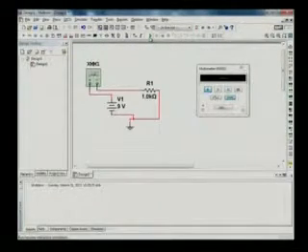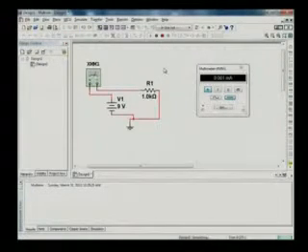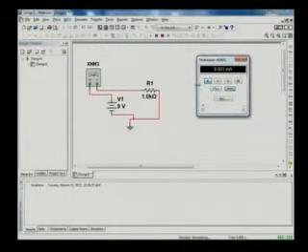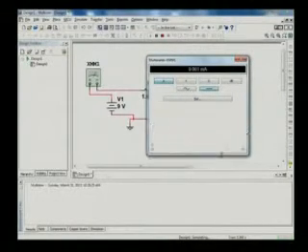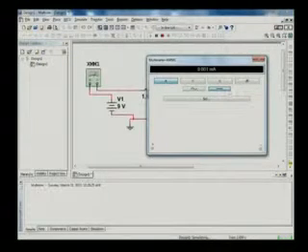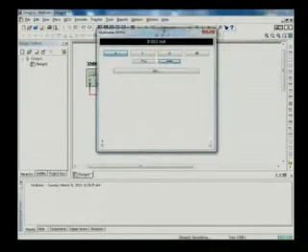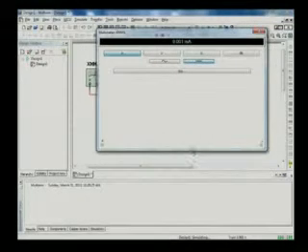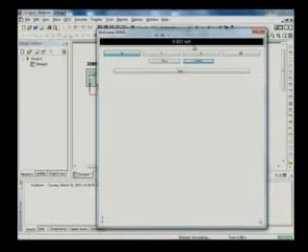I have completed this circuit and I want to check the behavior of the current in the circuit. I will just click once. If you see the current, you can see the value, that is 9.001 milliamperes. Theoretically it should be 9 milliamperes, and we have checked in Multisim software, it is giving us 9 milliamperes. So those results are matching, so we can be sure that our circuit will work. Then the next step will be to design this circuit on a breadboard.